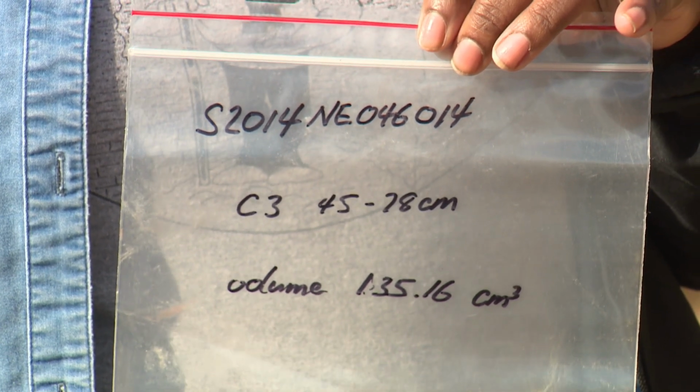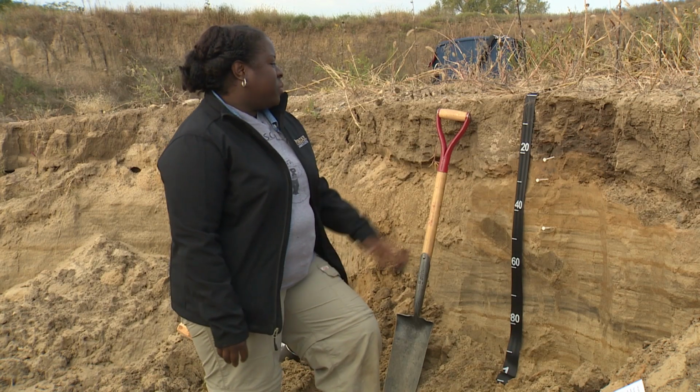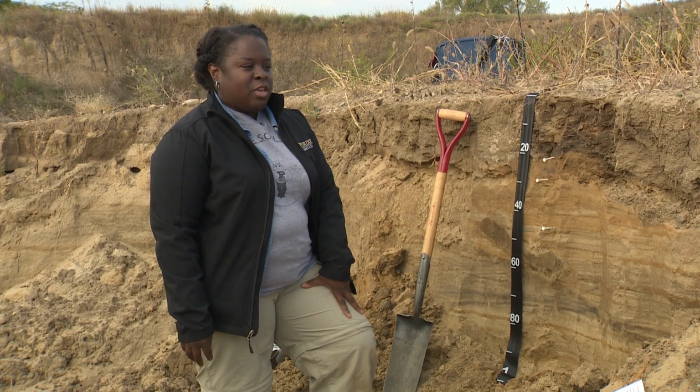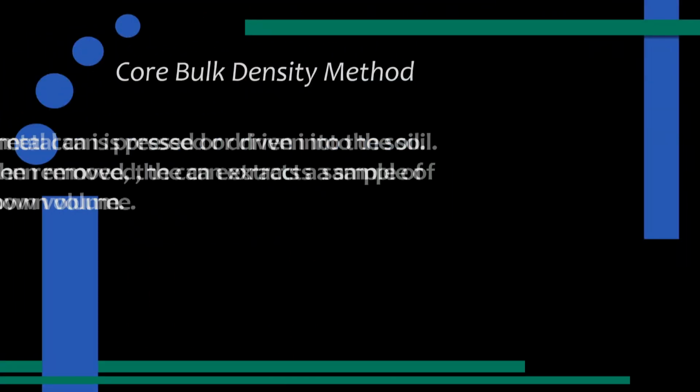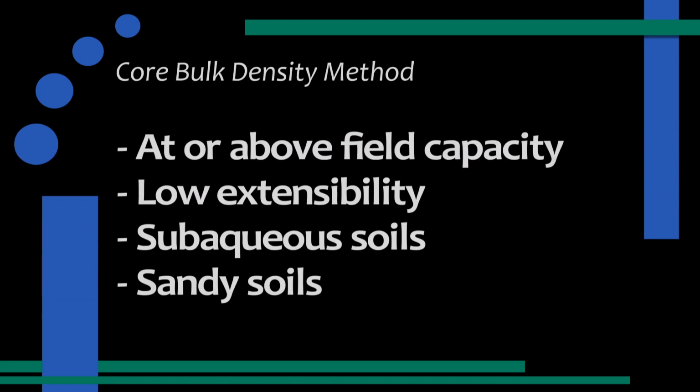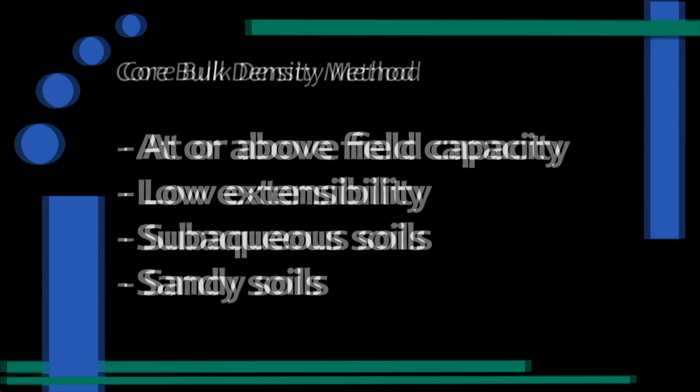This particular method is a pretty simple method that you can do if you're unable to take a clod sample. Using the core is really good for soils that have high field capacity, low extensibility, subaqueous soils, as well as soils that are sandy.